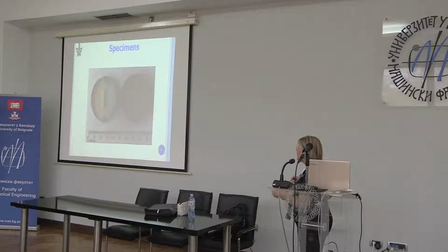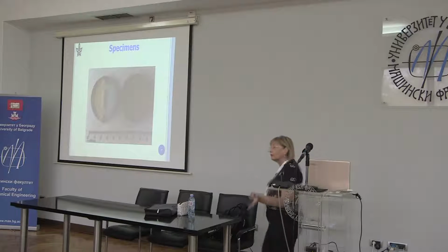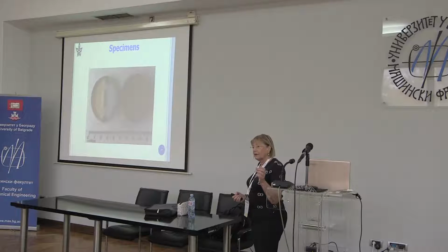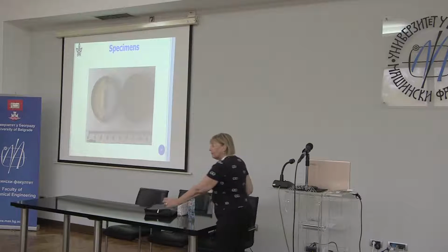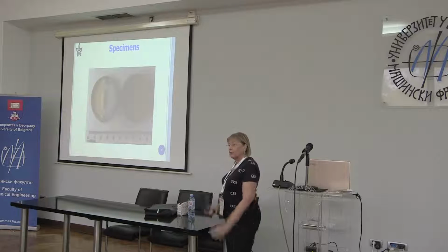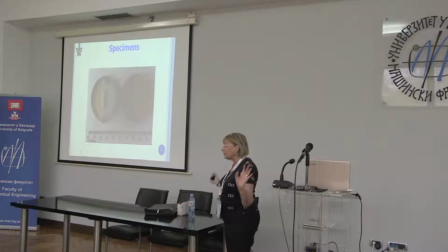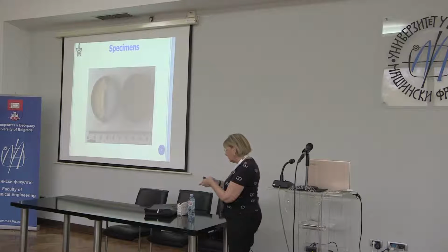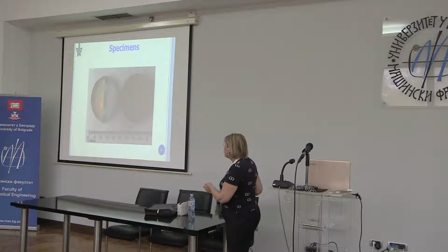And so we have epoxy, we have glass, we molded the specimens, and I don't know if you can see this, but there's a ring of aluminum which cut down on the residual tensile stresses at the end. The aluminum makes them compressive stresses, because what happened was, here we are doing experiments. I tell the technician, put the specimens on the table at night, and we'll come back tomorrow morning, and we'll be all ready to test 5 specimens. We come back in the morning, and they all have cracks. That was before we put the aluminum.